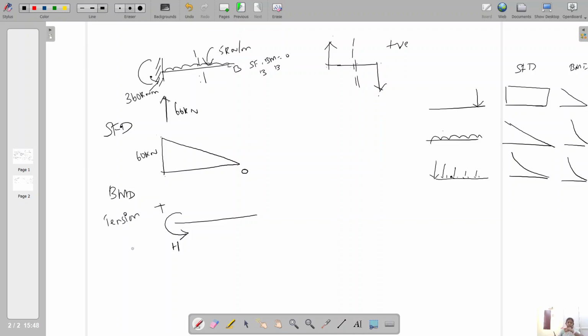That's why the reinforcement is provided on the top in the case of a cantilever beam, while in a simply supported beam the reinforcement is provided according to the moment direction, either at the bottom or at the top. But in a cantilever beam, the top reinforcement is provided to counteract this tension.